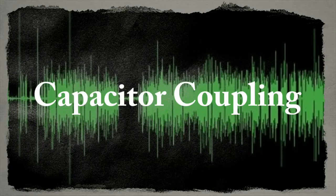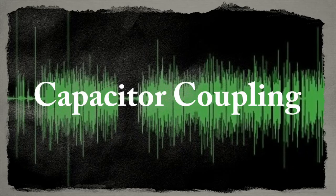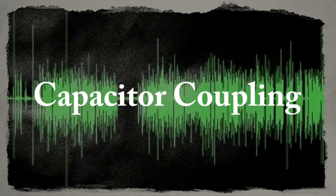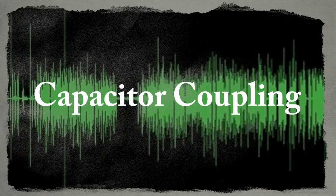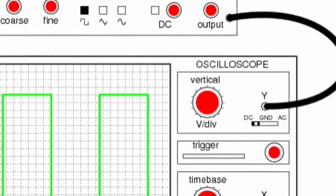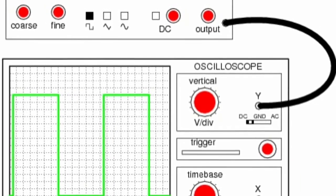Different parts of an electronic circuit are often coupled by a capacitor and a resistor. In this section we will work out what effect the time constant of the coupling circuit has on the waveform of the input. Square waves will be considered as the test waveform since they contain many frequencies. When square waves are pulsed into the circuit, the voltage across the resistor is measured.